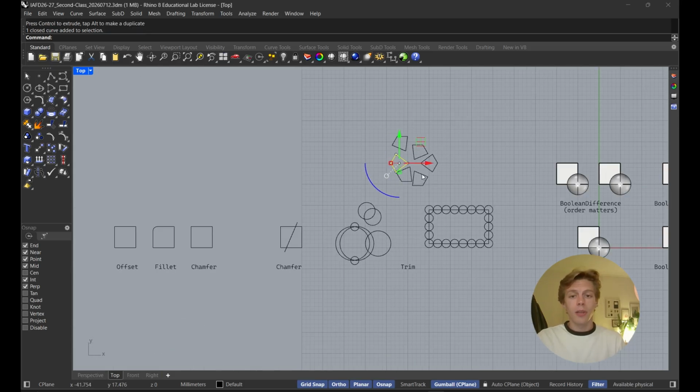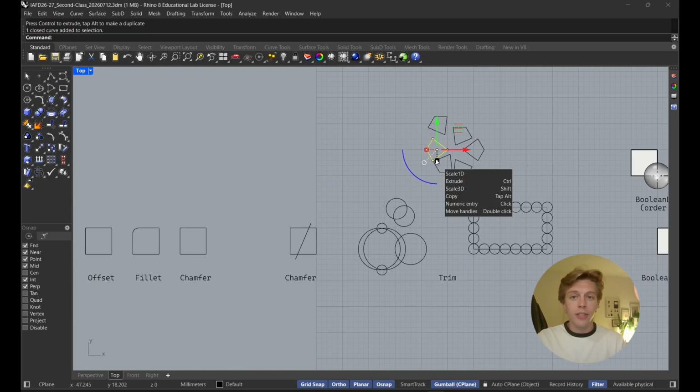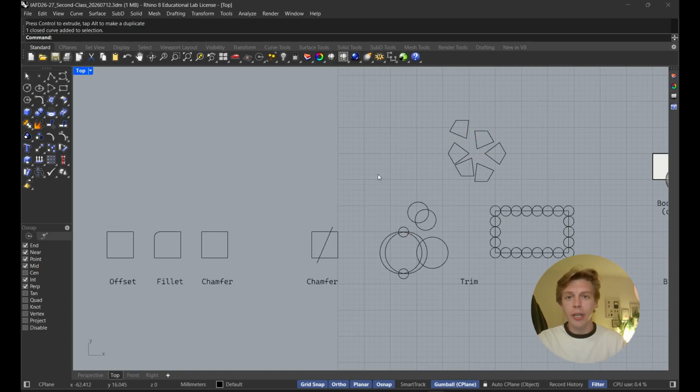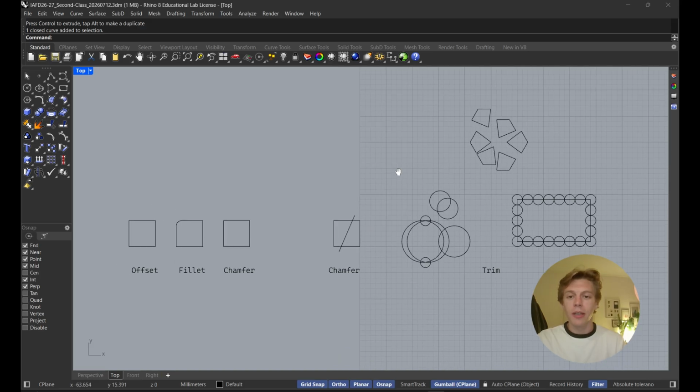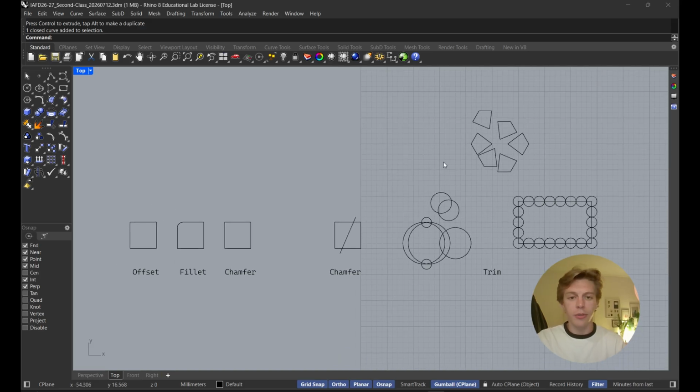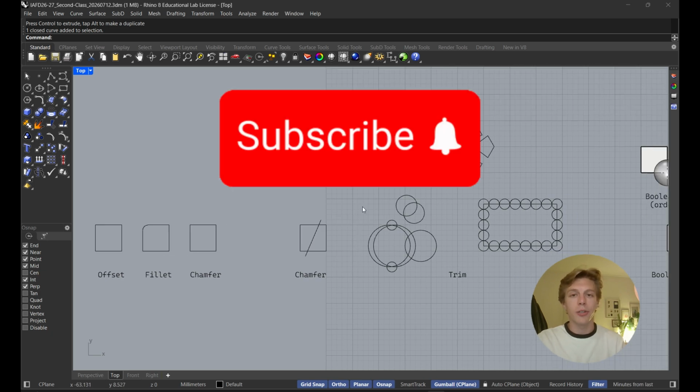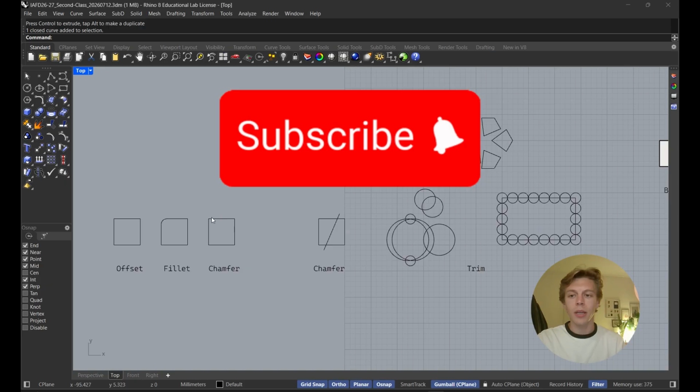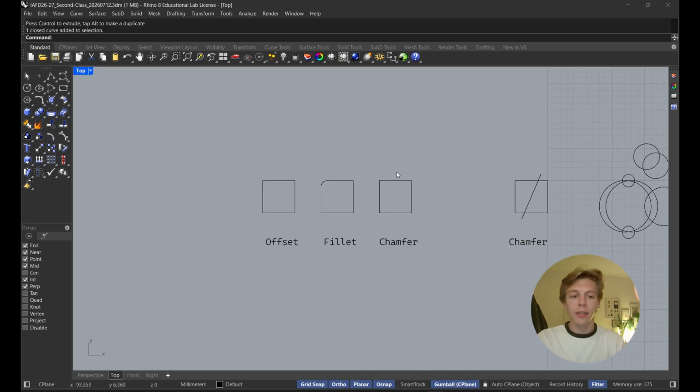Yeah. So again, as I said, this is a very short video, just exploring a few other commands. Feel free to try them out yourself. And if you need to go back to the video to see how it works, also don't forget, look at the conversation with Rhino, because it is always telling you what is the next step that you need to do. And remember that the order of selecting things like split and trim will matter, and fillet not so much.